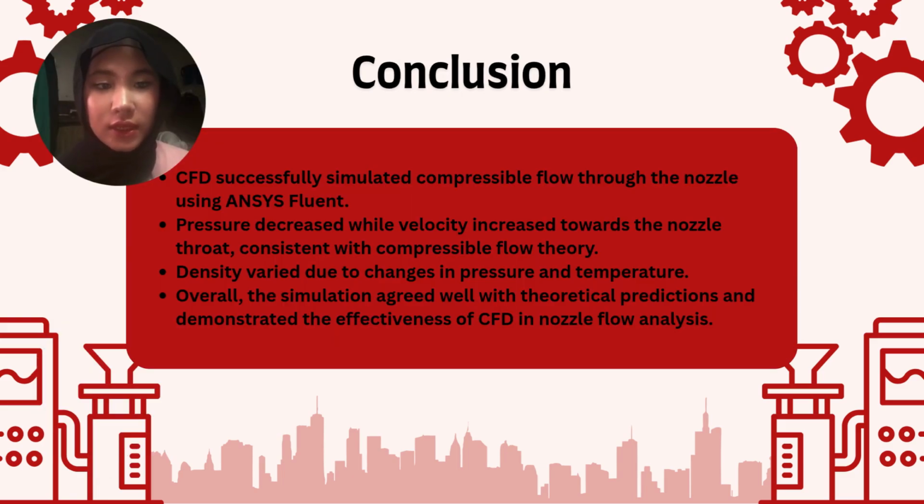So in conclusion, the CFD simulation successfully analyzed compressible flow through the convergent nozzle using ANSYS Fluent. The result shows that pressure decreased while velocity increased toward the nozzle throat, which agrees with the principle of compressible flow. Density also varied throughout the nozzle due to changes in pressure and temperature. Overall, the simulation was consistent with theoretical prediction, demonstrating that CFD is an effective and reliable tool for analyzing nozzle flow behavior. That's all from us.